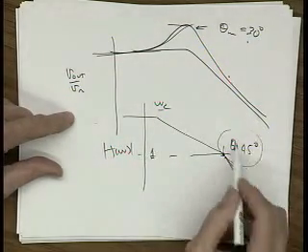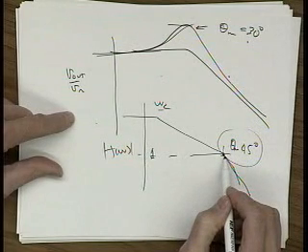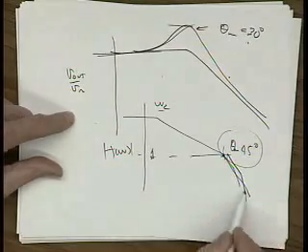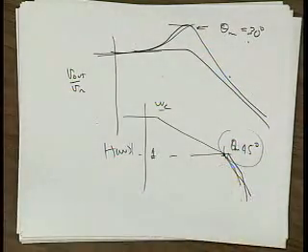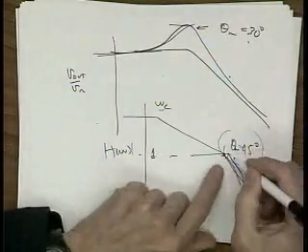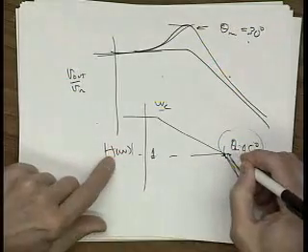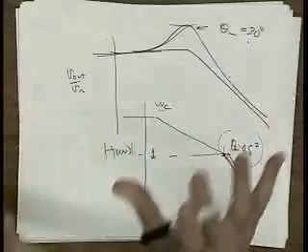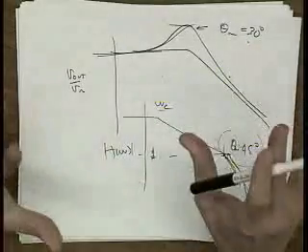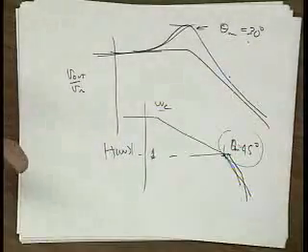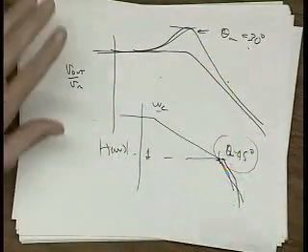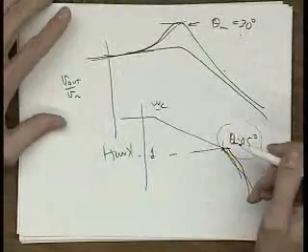If we check this phase margin number, it fortunately tells us a lot about what happens, even though there's lots of other poles out here that are moving all over the place when we put it into feedback. This phase margin number that we can check with this loop response tells us a lot about where the poles are after we close the loop. Okay, that's a big step. There's no reason you might believe that's true, because those poles are moving all over the place. But it is true, okay?